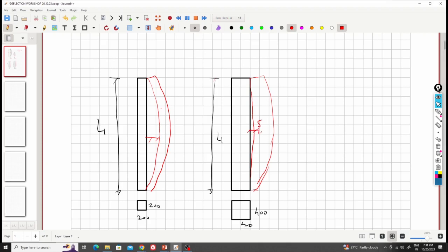This delta is less and this delta is more, even though height is same. Width is less. Yeah, so we can say the cross sectional area is more here and is less here. Right. So if the cross sectional area is more, and that too in the buckling direction, this depth is more. Try to understand, it is buckling in this direction, so the depth in this direction should be more in the buckling direction. So there is one term which is related with the cross sectional area A. There is one area A also, and this depth is more, that means the moment of inertia I is also more. Try to understand this.